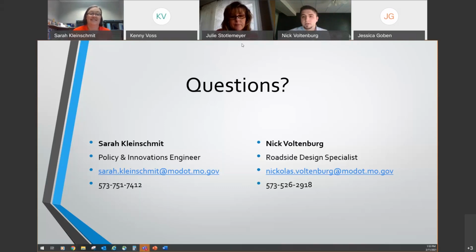Sarah, I am actually going to refer to you on that one, if you don't mind. I think Darren's also present if he needs to help with that one. Yeah, I might tap Darren for that as well. It's my understanding that you can use dowels in a retrofit type situation, but we want to make sure that we're still getting enough dowels in there, and that we're using an epoxy adhesive to also help with those shear moments.